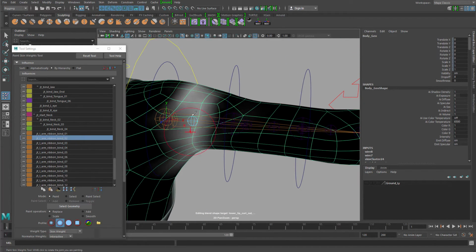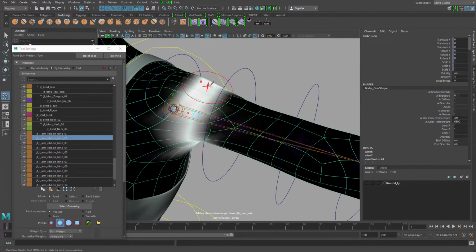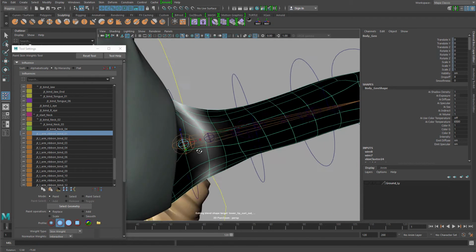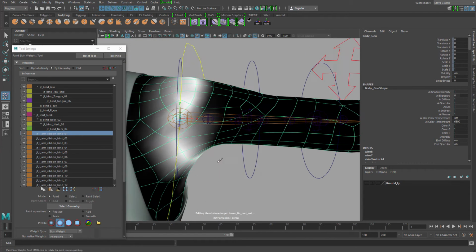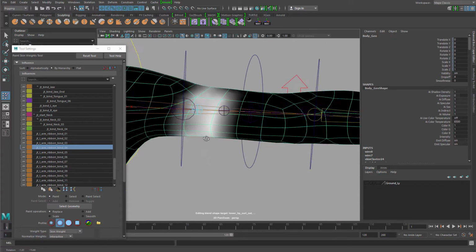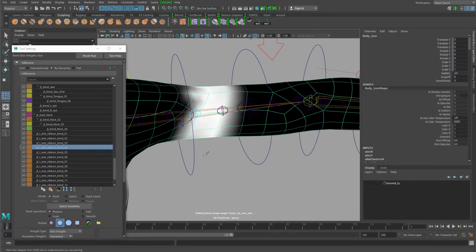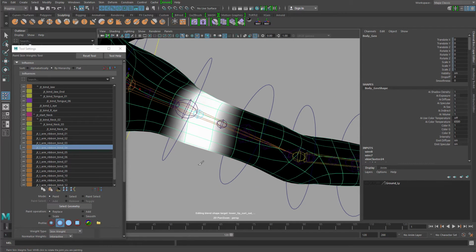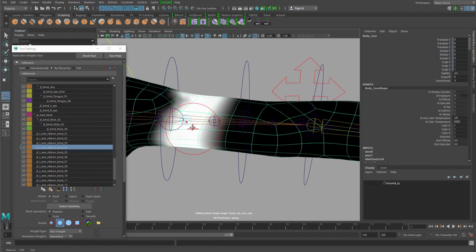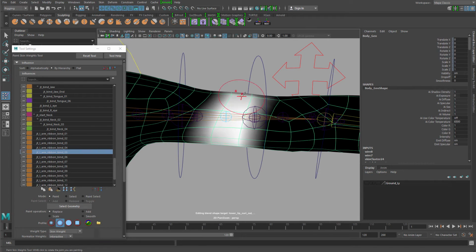Okay, 02. I think I'm eliminating all 02 by painting 03. What you want to do is go back and forth, making sure you're taking care of all the area here. 1, 2, 3. Let's go on to 4. It's going to take maybe that line. You want to give it a value of 1 and then just overwrite the weighting here, because if you don't, those weightings will still belong to the original bending joints, which is not good.